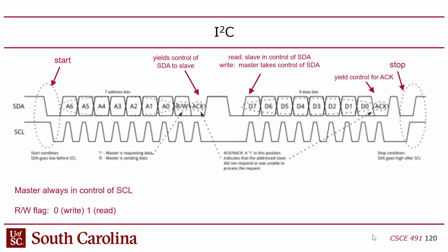The CAN bus is similar, except CAN is controller area network. It's used in cars. And so the CAN bus, instead of this open driver, actually uses a differential system. There are 2 wires. When those 2 wires are shorted, that's a 1 bit. And when the 2 wires have a voltage between them, that's a 0 bit. And then the CAN bus has a little bit more complex packet structure. It has more fields in it. But it works in a similar way. It's multi-master. And CAN is really cool.